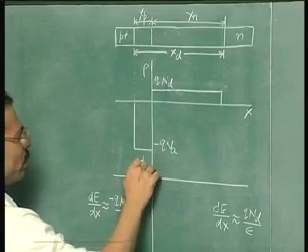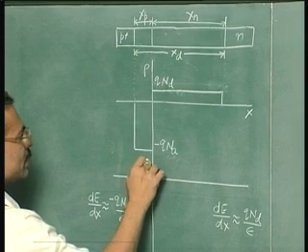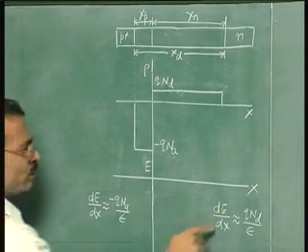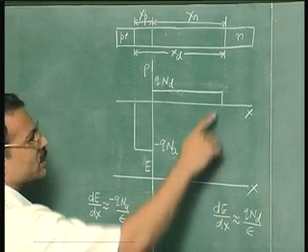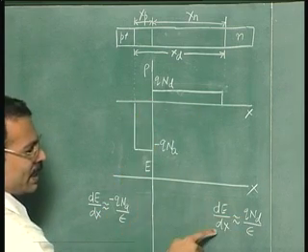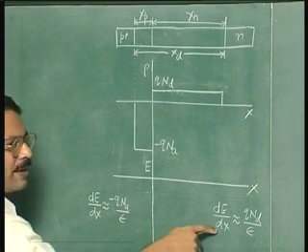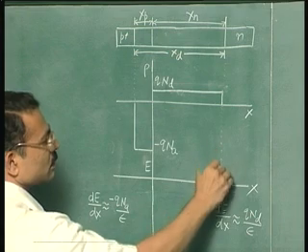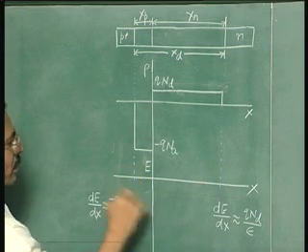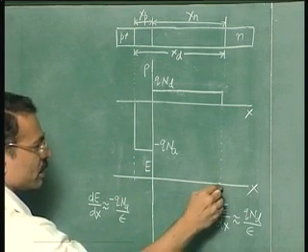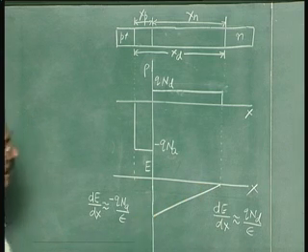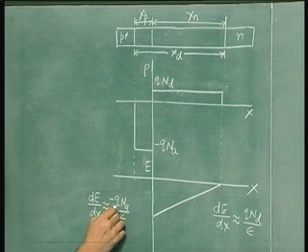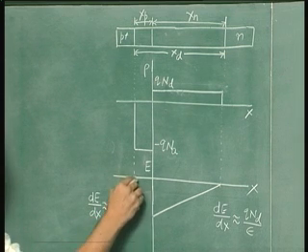So which means that if I want to sketch E versus x, I know from here that since q Nd by epsilon is constant over this distance, dE by dx is constant, that means I should have a straight line for electric field as a function of x. So this straight line has a positive slope. So this is the way one can draw this straight line on this side. On this side, the slope is negative, minus q Na by epsilon. So it is something like this.